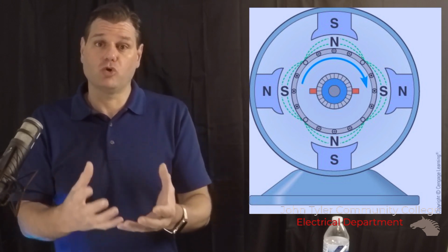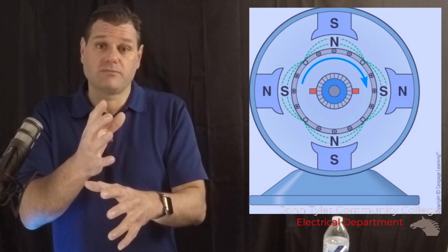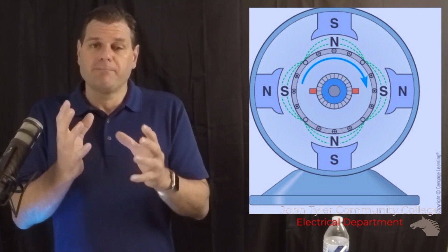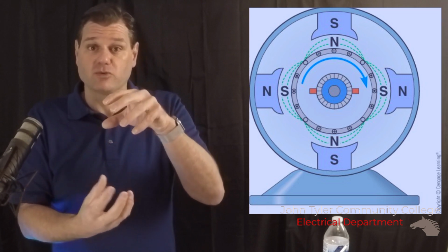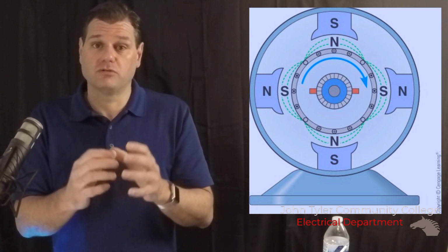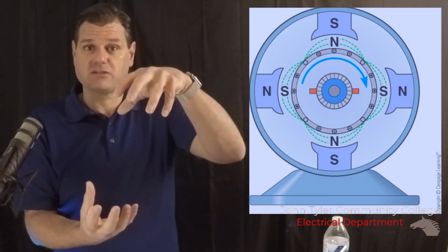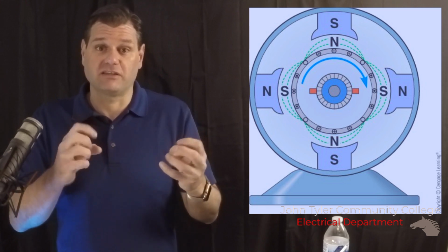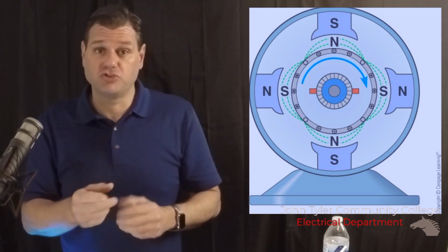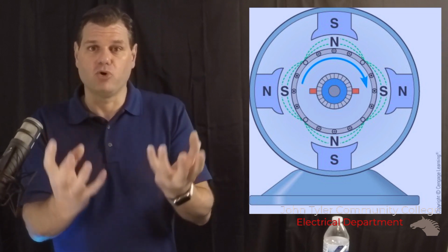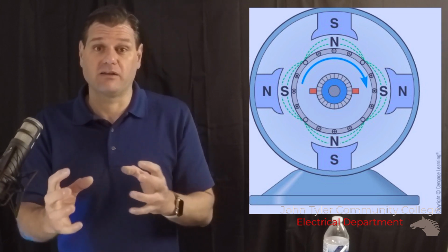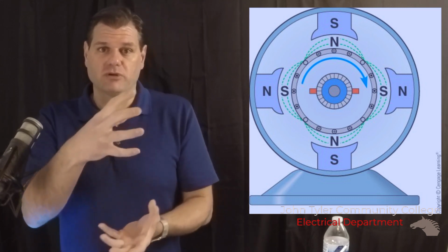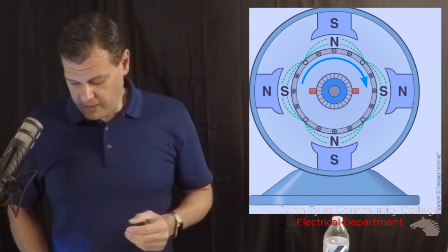So the more electrical load we add to the generator, the more this twist happens. So the more you load it, the more that twisting rotational effect happens. And these smaller magnets, which have no effect on the actual device itself, because by the time the brushes get to these little tiny magnets, they have completely disconnected from the main coil, so they have no effect on the actual generation, but they're allowed to pull that magnetic field back, and they're kind of like a steering magnet. They're going to pull it back into the right position. So the more current, the more twist, the stronger those magnets will be, and pull it back in. So you kind of get the idea how that works.